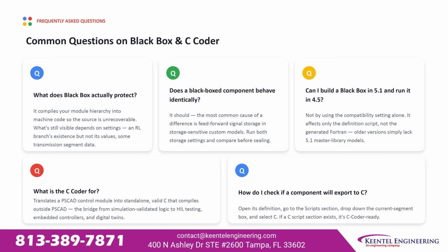Does a black-boxed component behave identically to the original? It should. The most common cause of a difference is feed-forward signal storage in storage-sensitive custom models. Run both storage settings and compare the results before sealing.